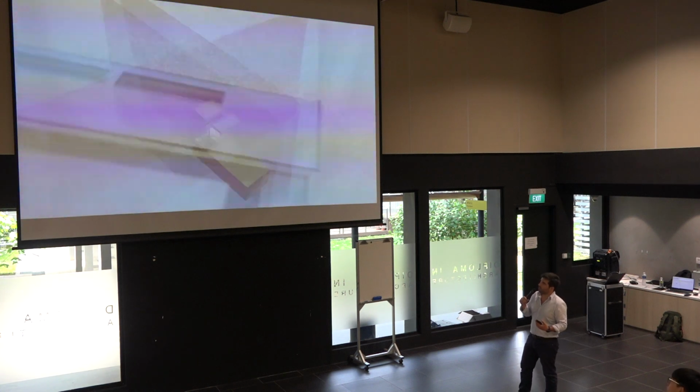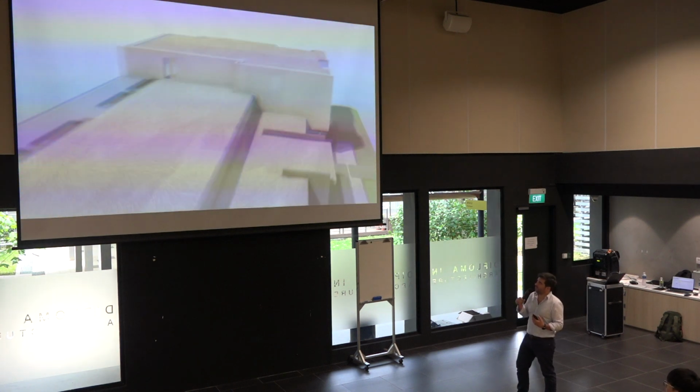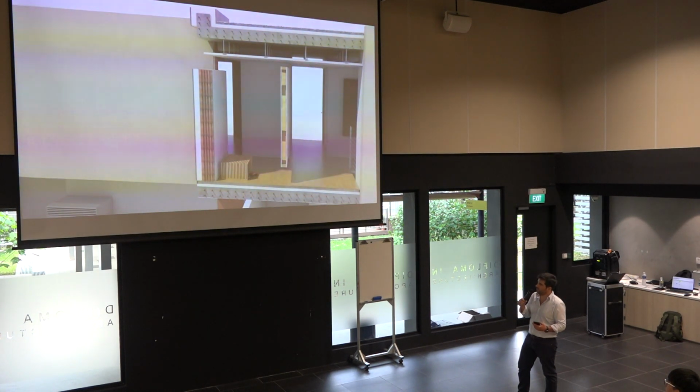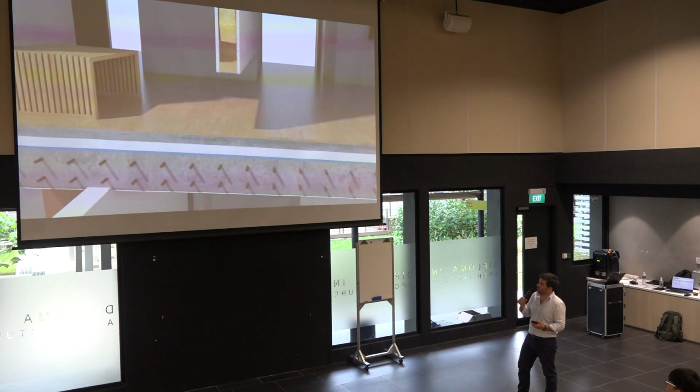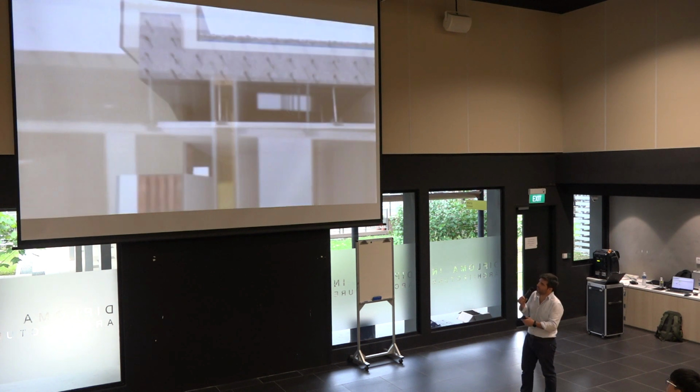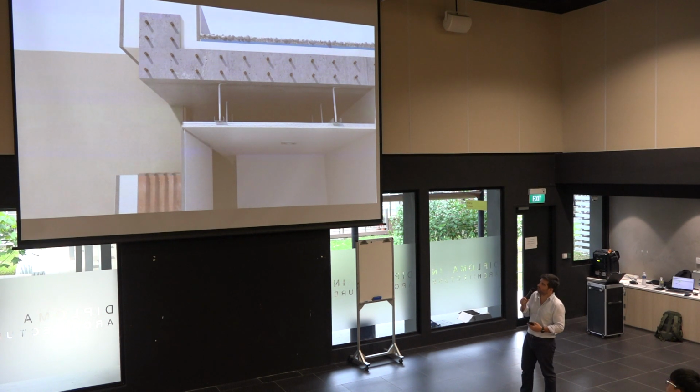In this next example, if a wall is a stud partition, it will have less priority. So when we model it and it touches the ground, it will only deduct the finish of the floor. It has more priority than the suspended ceiling, so it will go through up to the concrete.